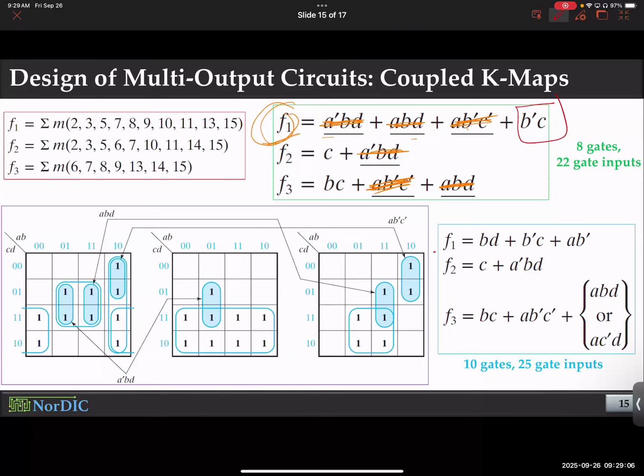As opposed to, if you go for this functional output, how many gates will you need? Yes, 1, 2, 3. So you need 2 more to implement this function, which looks simpler. But practically, if you think about the hardware implementation without sharing, that practically needs more gates. And that's why you see, you save, instead of 10 gates, you need 8 because you got rid of 2 gates by sharing. So it looks more complicated in functional form, but practically it is simpler.